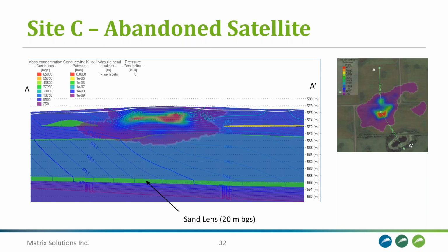One thing is we have those upward vertical gradients, and so the movement of chloride is mostly up and down in the soil profile. And because of this, if we did go ahead and just do that root zone soil excavation, the value would be limited, as there'd always be potential to re-impact the clean stuff on top with the salinity that you're leaving down below.